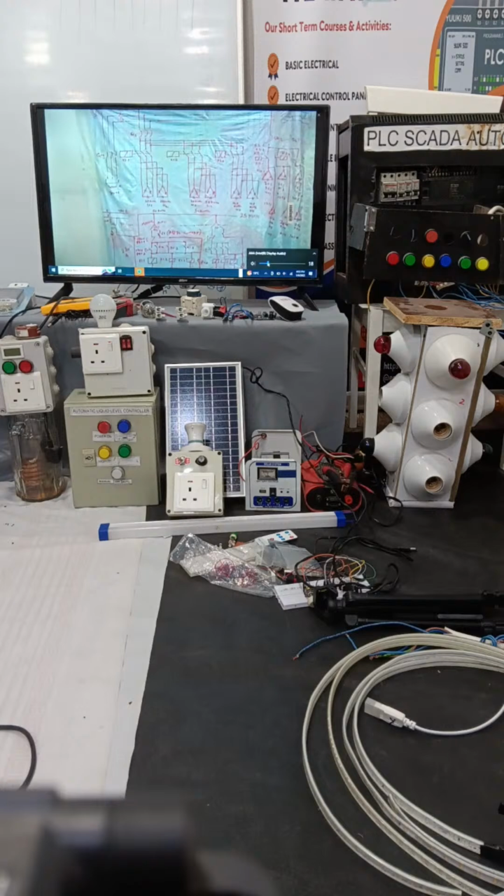The contactor is like a magnetic switch. When the coil is energized, a magnetic field forms and it pulls the moving part, so one fixed part and moving part get closed here. Since there is a pilot light parallel to the coil, it gives indication that the contactor is switched on. Obviously, when the contactor switches on, the capacitor will be charged. So when this PL1 glows, it indicates that the capacitor banks are on.